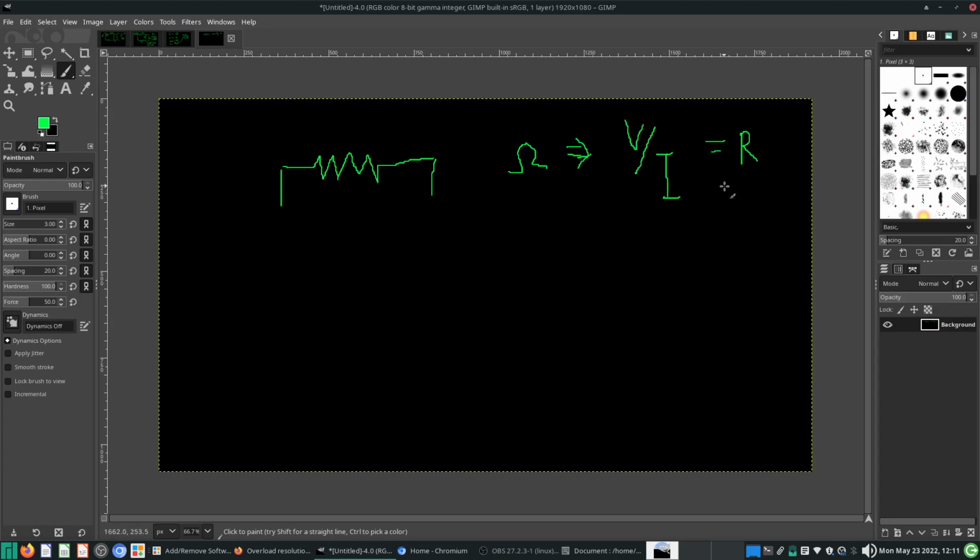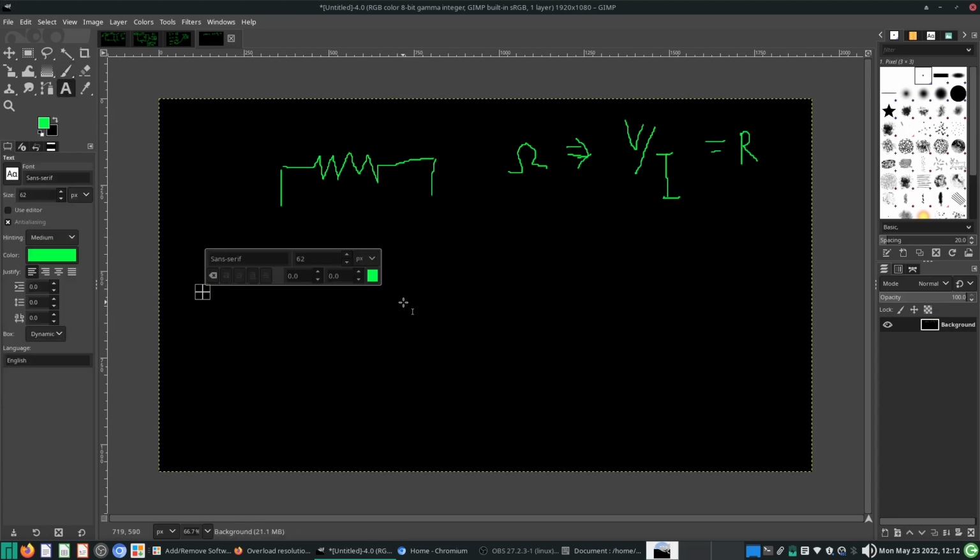You don't really change the resistance, no matter what the voltage is. Okay, if the voltage is 5 volts and the resistance is 2 ohms, then the current will always be 2.5, for example. If you increase the voltage to 10 volts, and your resistance is still 2 ohms, then you will get 5 amperes. Okay. However, for fluid flow, flow resistance will not work out like that.